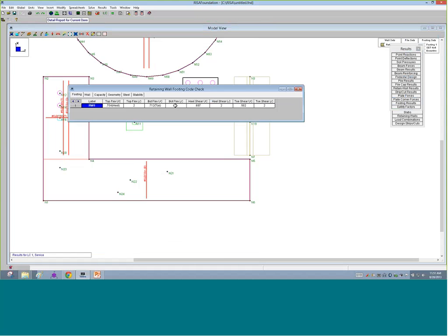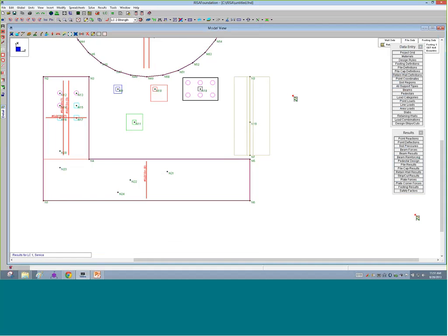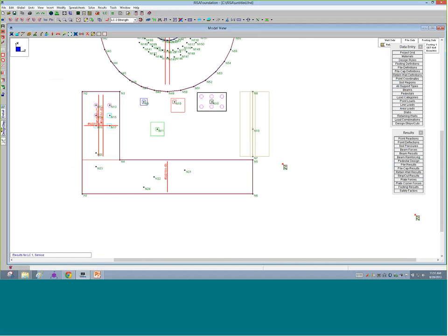So you can always take a look at your results toolbar, which is floating around on the right side. The retaining wall results are listed here. We can go into each different capacity, the wall, the capacity. So very similar information to the detail report, except a little bit more condensed and quick and easy to attain. So that red number we saw, the 1.641, is listed right there, and we would see that really fast in the retaining wall report. It's kind of easy to see it that way.